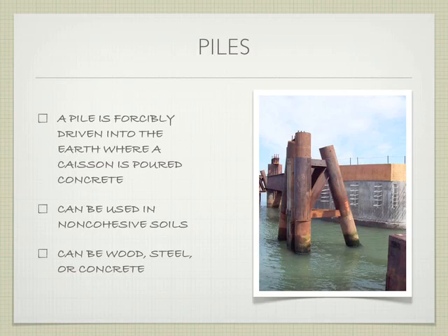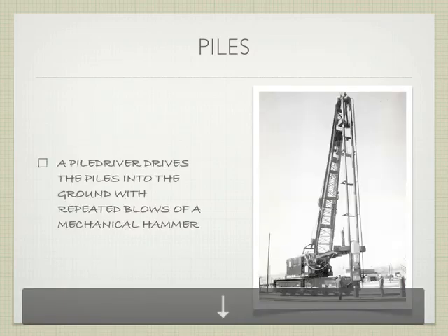Okay? The best part about a pile, right, is you can use it in non-cohesive soils or cohesionless soils. Right? If I'm in sand, no problem. I can drive a pile. Right? If I'm in a combination of soils, I have some clay, but I have some sand, I can still drive the pile. Right? So it's a little bit more universal. Okay? The problem is they can't be as large. Right? Because they have to be driven.